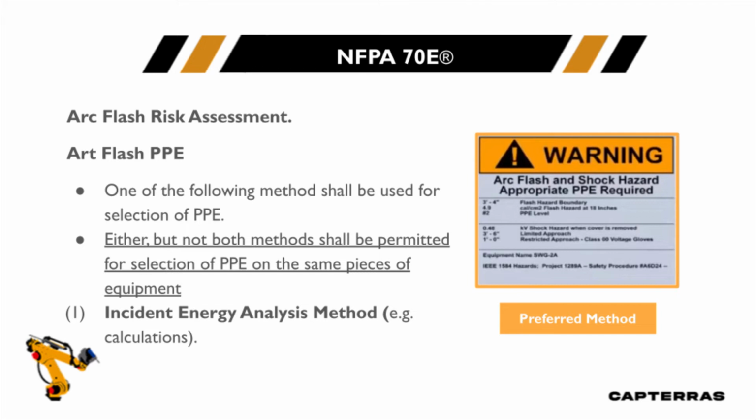In many cases, for many clients, we're leaving the PPE level off as well. And why is that? Because if we're at 7.9 cal and we indicate level 2 in a facility, or we may call it in many cases if it's a facility custom PPE level A, B, or C, we don't want someone walking up and saying 7.9 cal, but ignoring that, just putting a level 2 on. I'd like them to see the 7.9 cal and be trained to understand, whoa, maybe I should wear something a little higher than 8 calorie here because of all the variables involved here.